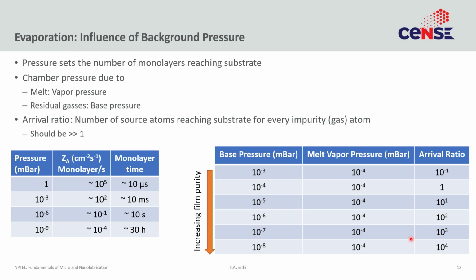No matter how hard you try, you are never going to get 10-9 purity of the deposited material, something that CVD gets easily, right. So that is the limitation of the physical vapor process. The background pressure always introduces impurities that are very hard to reduce, and getting to very low vacuums is very hard and expensive.